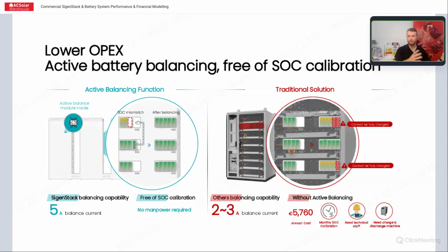But if you fast forward 5-10 years down the track, you're seeing varied performance across the modules, which is just natural in any electronic components. In a stack that's in series, for example, if one cell or module gets down to 1% and you still have modules at 20, 30%, that's an exaggerated example,